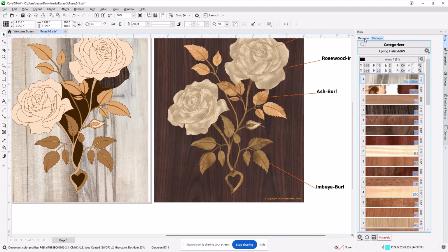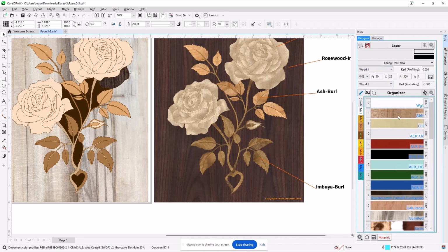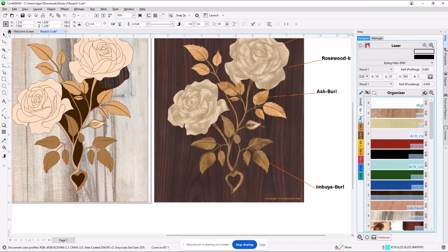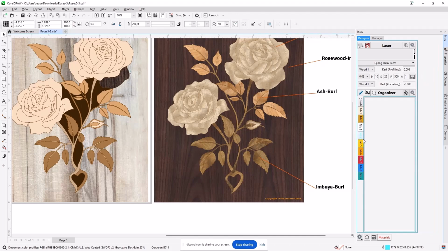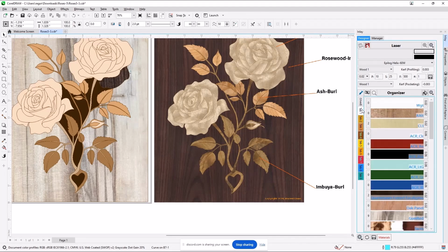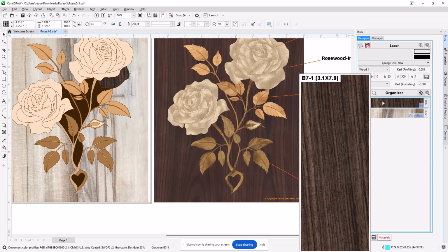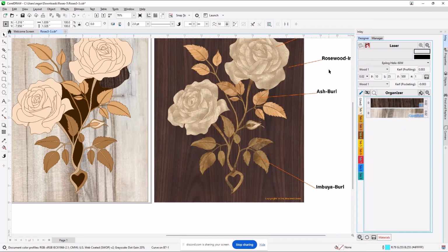What I'm going to do now, rather than drag this out too much longer, is go ahead and actually do the design. Now, in the default behavior for any library that exists, it comes up with the materials loaded under these different tabs, including the virtual materials. So you have the ability to use palette. When I select a material for the design, it goes over here. The background I chose and this dark wood veneer, both are now available under the Use tab. So once you get going on your design, you've got these items loaded, you can just use the Use tab for the rest of the activity.